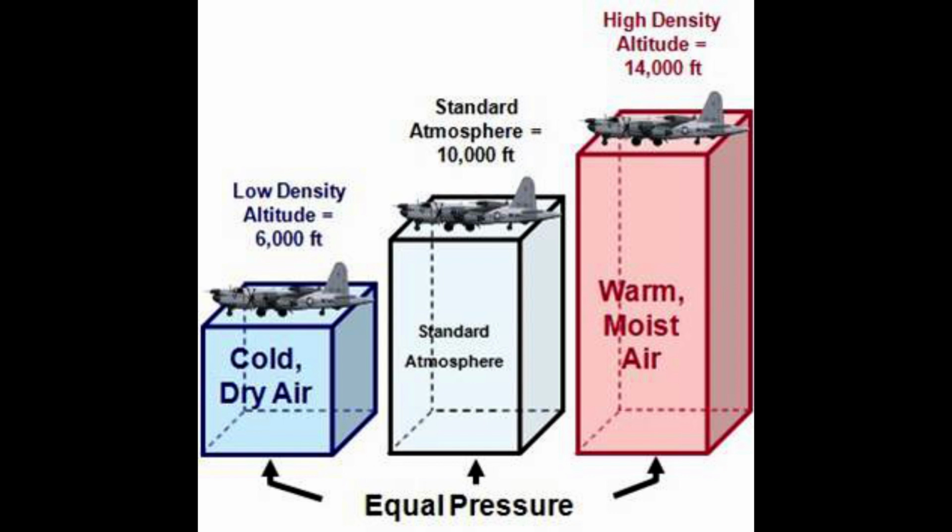Under conditions higher or lower than standard, these levels cannot be determined directly from the altimeter. Density altitude is determined by first finding pressure altitude, and then correcting this altitude for non-standard temperature variations. Since density varies directly with pressure and inversely with temperature, a given pressure altitude may exist for a wide range of temperatures by allowing the density to vary.